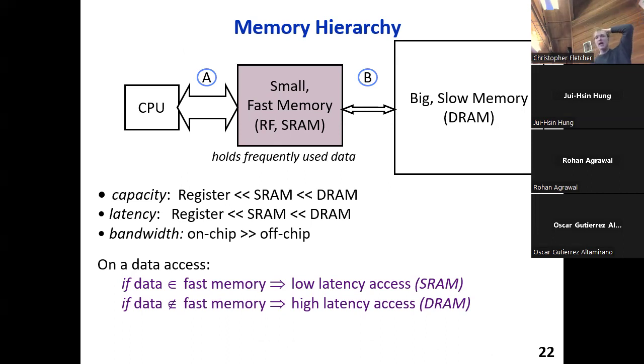This is DRAM. And then closer to the CPU, we have a pyramid of smaller memories. Only one step in the pyramid is shown here, where each step in the pyramid is successively smaller and features less aggregate capacity and potentially lower density cells, which contribute to lower access latencies.